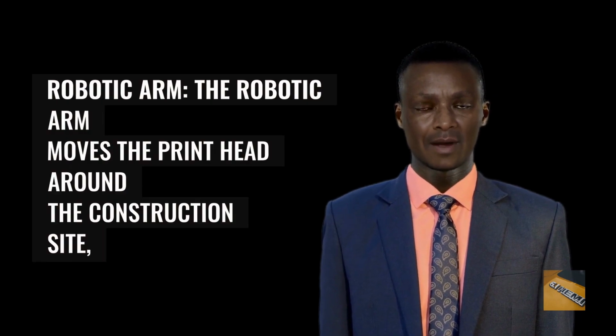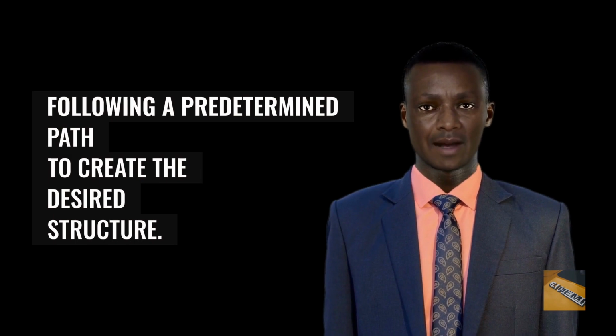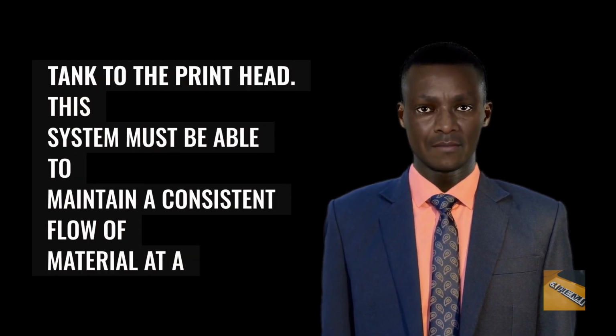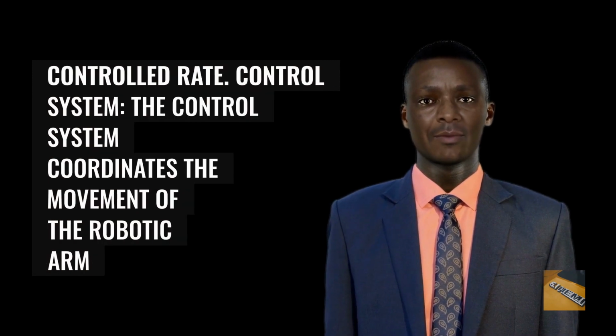Robotic arm. The robotic arm moves the print head around the construction site, following a predetermined path to create the desired structure. Material delivery system. The material delivery system pumps the concrete mixture from a mixing tank to the print head. This system must be able to maintain a consistent flow of material at a controlled rate.